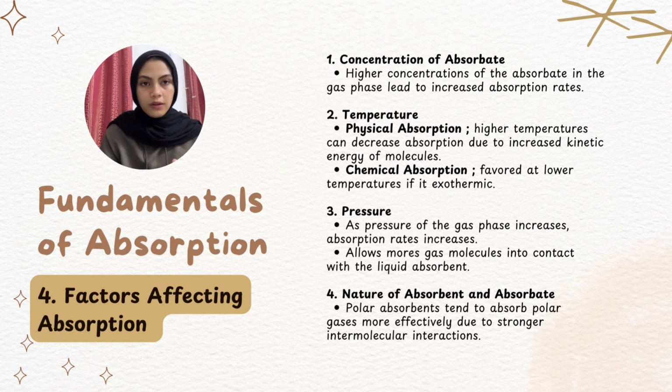And the third one, pressure. So basically we know that as the pressure of the gas phase increases, absorption rate also increases, and it allows more gas molecules into contact with the liquid absorbent. And then the last one, we have nature of absorbent and absorbate, where polar absorbent tends to absorb polar gases more effectively due to stronger intermolecular interaction.